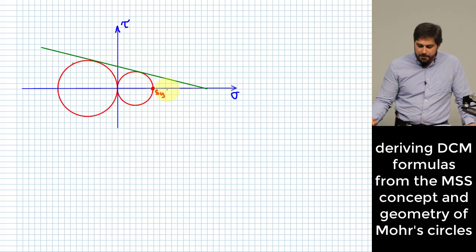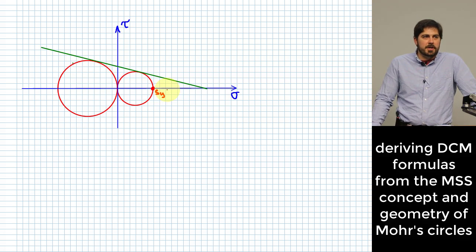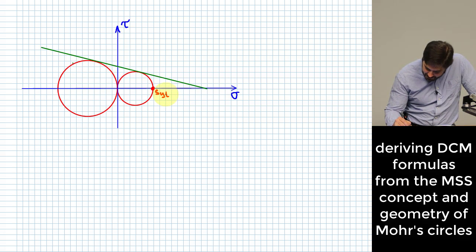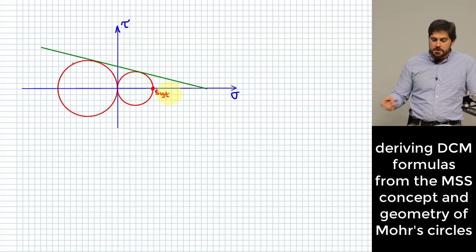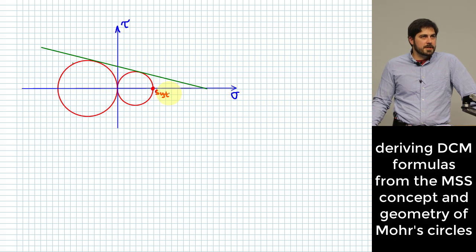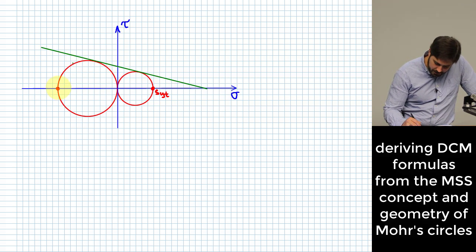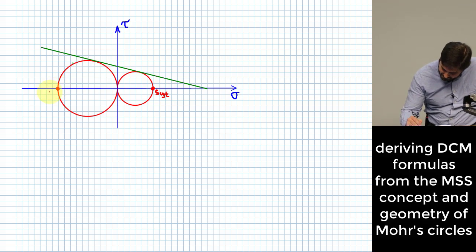Actually, we need a little bit more notation than this because we're going to have two different yielding strength values in this problem. So why don't we call it S sub y t, because that's our yielding strength in tension. We can also do material testing such that we apply the force in a compressive orientation, and you can do the same thing and load it to the point where it will yield. And so that would be this point back here, S sub y c.